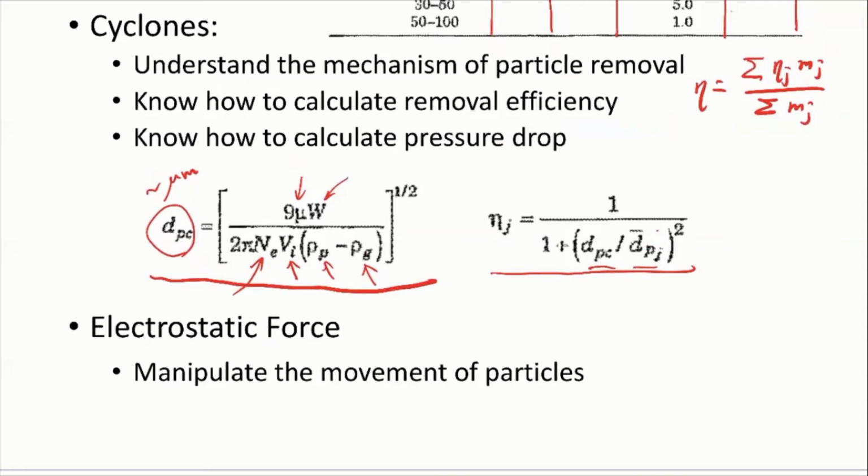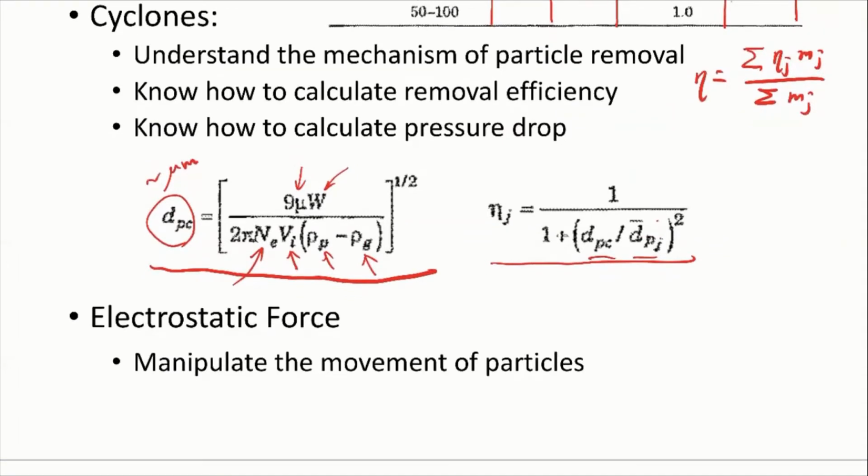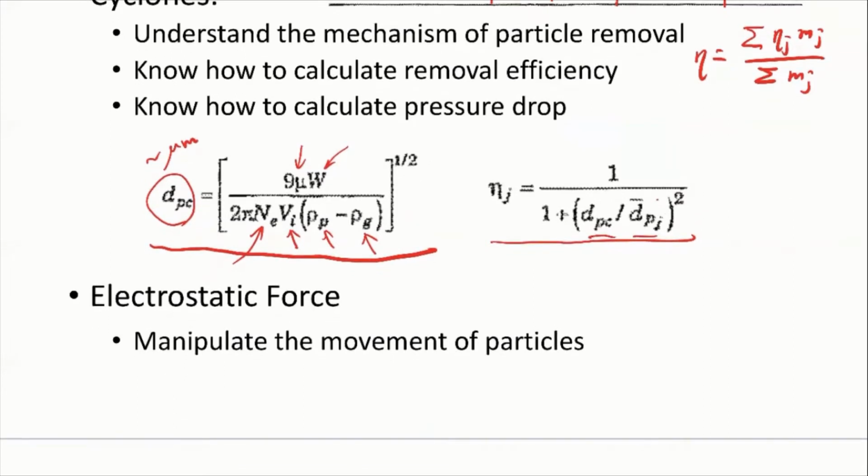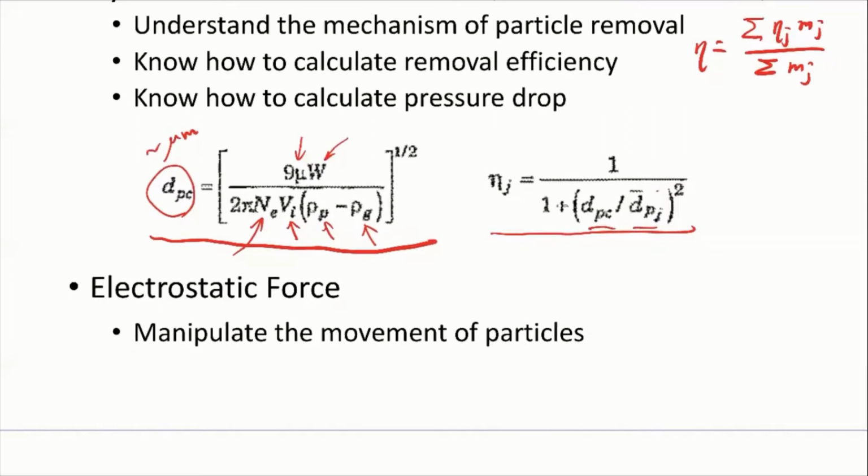At the end of last class, we also mentioned the electrostatic force, because to remove the particle with the electrostatic precipitator, we need to use the electrostatic force. And we used the electronic book or the Kindle as a simple example there, right? We saw that people use this electrostatic force to control or manipulate the movement of the particles under the electric field. We also demonstrated that under the reasonable condition of a Kindle, let's say an electronic ink device, the response of the ink for refreshing a page, let's say flipping the page, is quite slow, right? It takes around 0.25 seconds.